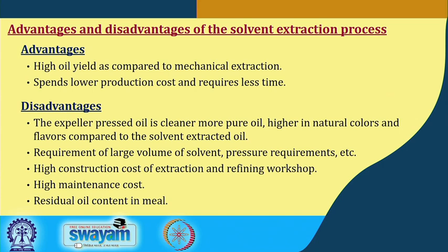The solvent extraction process has the advantage of giving high yield as compared to mechanical expression, and we can get oil recovery as high as 98-99% in solvent extraction, or even more. It has lower production cost and requires less time. However, there are certain drawbacks of this method as well.